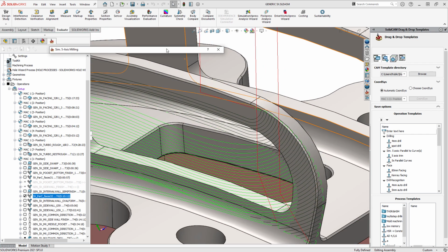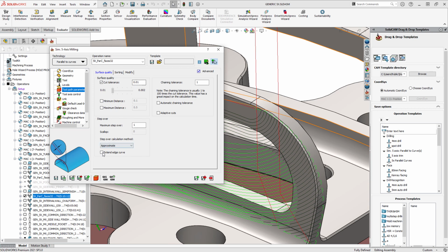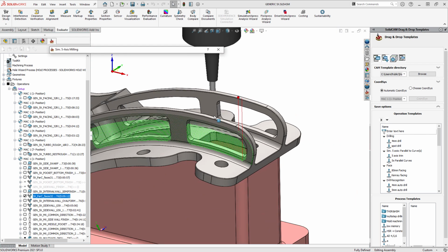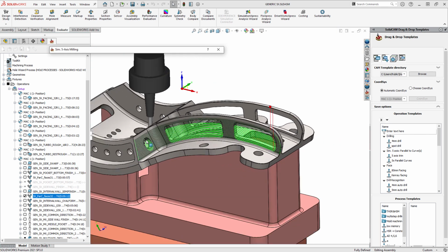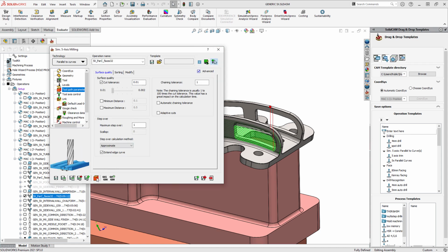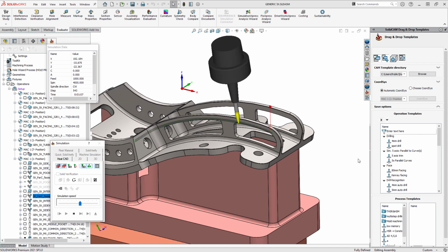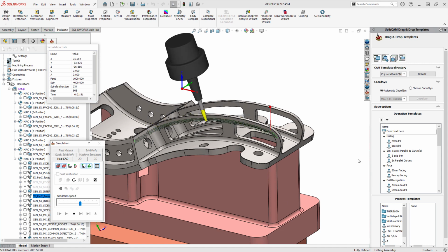In SolidCAM 2021, we now have the added ability to extend the edge curve to match the longer defining feature of the selected geometry. This simple enhancement makes for a better defined toolpath, keeping consistent cutting conditions across the full face of the feature. Albeit simplistic, this is a feature which will improve the capabilities of both the HSS and the multi-axis operations within SolidCAM.